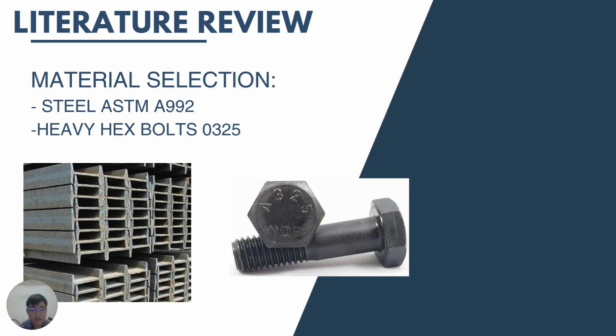The yield strength of ASTM A992 is approximately 345 megapascals, which allows it to withstand a large amount of stress without failure. Dynamic loading conditions that bridges face, such as traffic loads and environmental forces, require material that exhibits both high tensile strength and fatigue resistance. Steel ASTM A992 satisfies these requirements, ensuring that components like beams, girders, and columns remain stable under various load conditions.